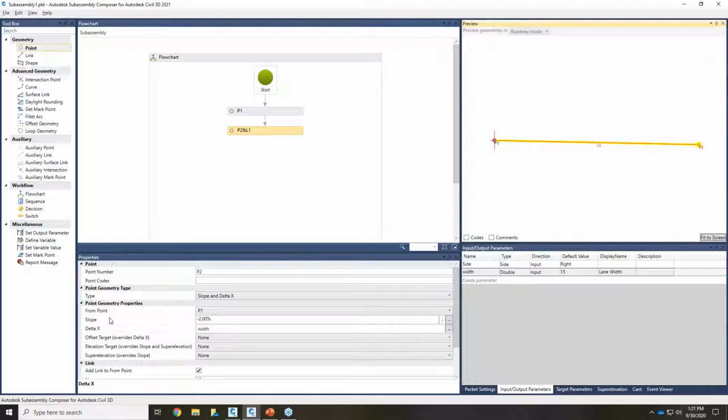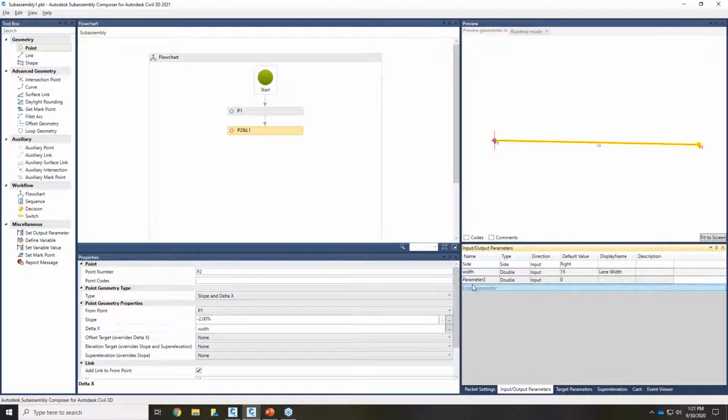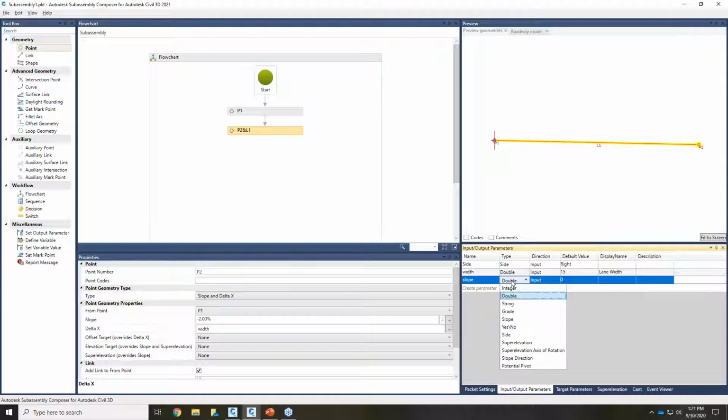All right, let's do the same thing for slope. So I'll create this parameter for slope. All right, so I'll do default slope. And slope is going to be measured as, let's say, a grade. But that's a percent. So I'll say a grade of, by default, 5%. And that I want to be able to go 5% positive or negative.